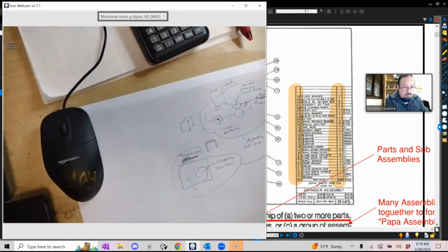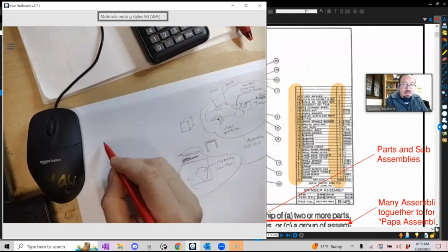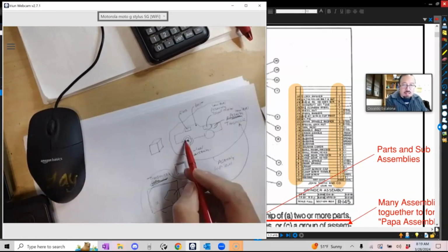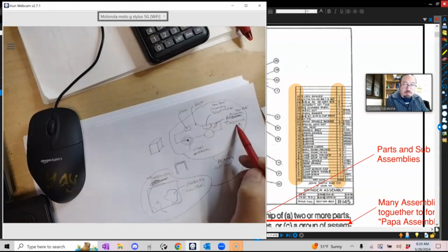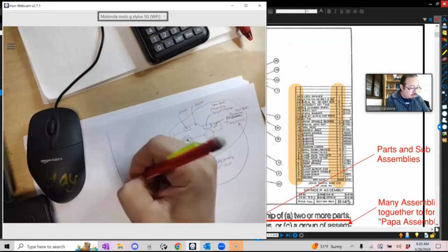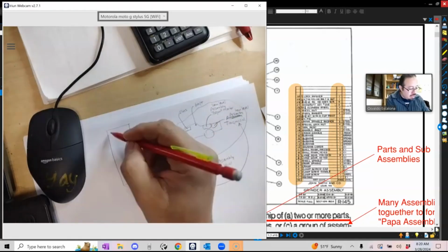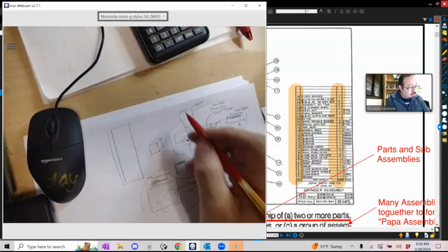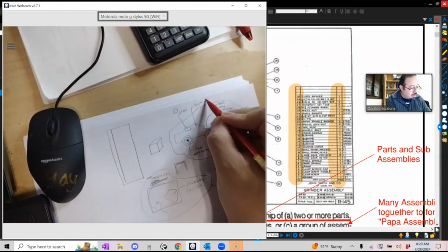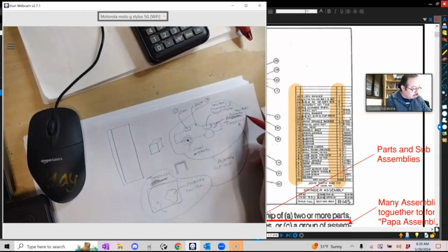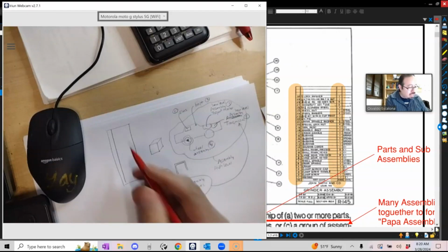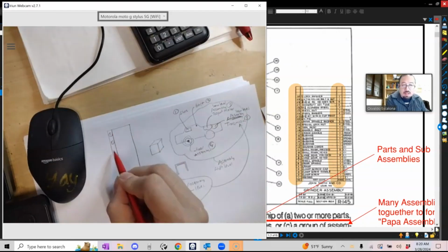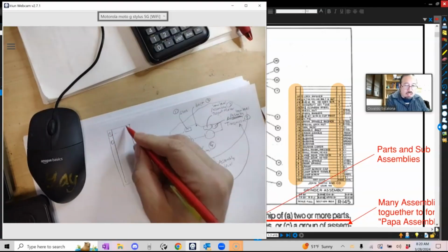So, for example, you have your car. Let's go with the car, right? That car has a subassembly, or a low-level assembly, or subordinate assembly. I'm going to make a list, and in here I'm going to put a bubble. Bubble 1, bubble 2, bubble 3, bubble 4, bubble 5. You continue putting bubbles all over the place. You will again have a description, and you will have the quantity.